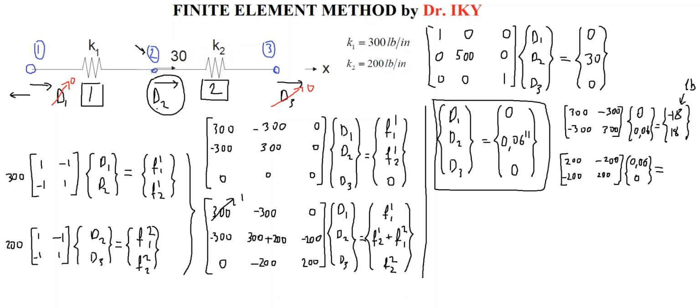After that, if you look at the total external load, it was 30 pounds. Initially, we found for the first force it is 18 pounds. It means that you have 12 pounds left, which you can also calculate from here. 2 multiplied by 6 is going to give you 12. Let me write it here. You have to consider the directions also. You should combine 18 with 12, which is going to give you 30 in total. And for the second row, because of the opposite directional system, it will be minus 12.